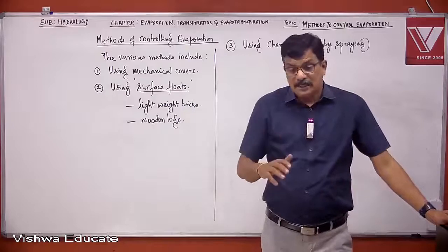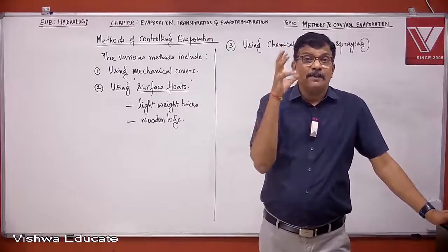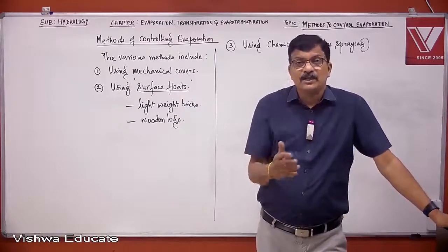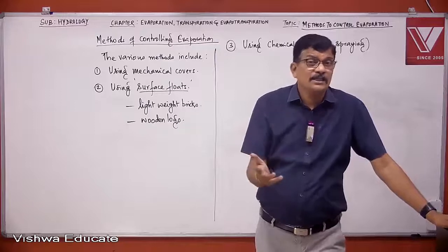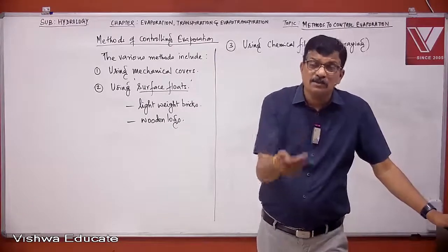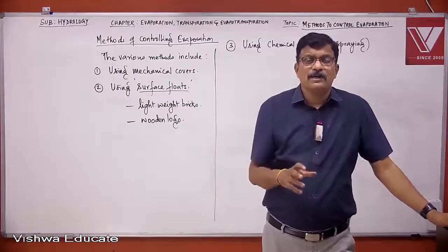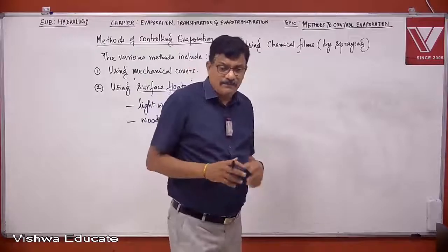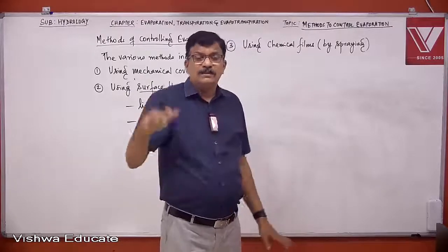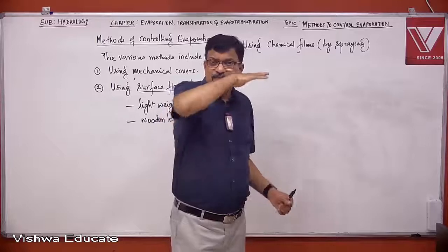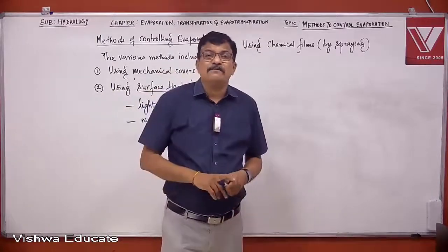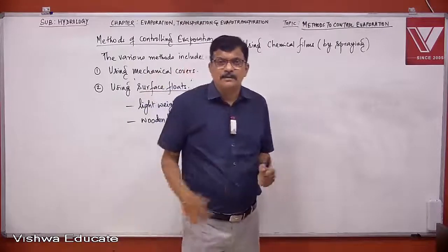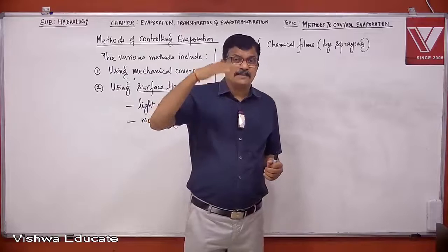They should not affect the palatability characteristics of water. Palatability means the appearance. They should not change the color, the taste. They should not impart bad taste and odor to water. So all this needs to be protected. Such chemicals or chemical solutions that we spray over the water body act as a chemical film. You get a small film of this chemical on the top. Again, that will act as a barrier.